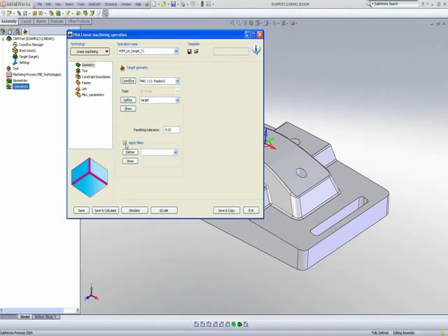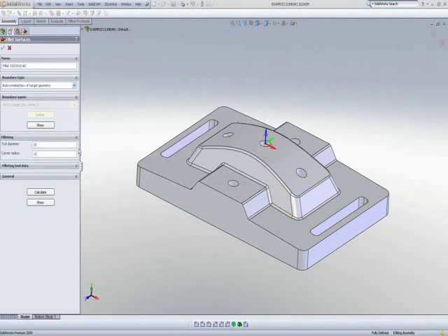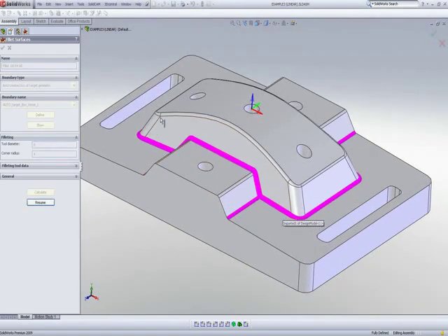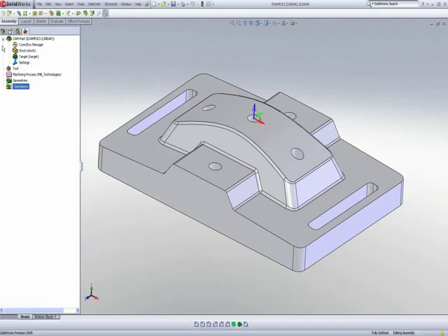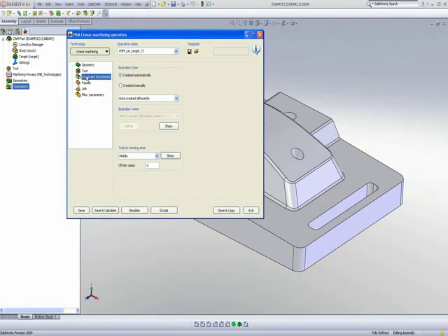I'll simply do apply fillets. In my define area, I'll simply say as if we have an 8mm ball end mill going on that part. Now when I calculate that radius, you'll see that we'll have a bigger radius on the part itself. If I press show, you'll note that I built a radius around the entire part. Now, I'll accept this.